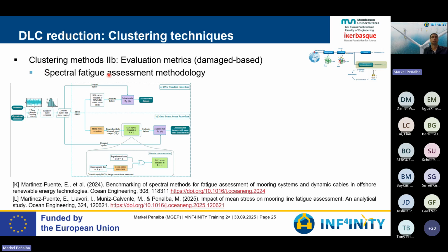on some spectral analysis. I included here a couple of publications where we have developed these spectral fatigue assessment methodologies, including mean stress, which is important in specific applications like moorings, for example. And you will find in these links all the codes required to compute these spectral fatigue assessment methods, instead of using the more common and more computationally expensive rainflow counting technique, the